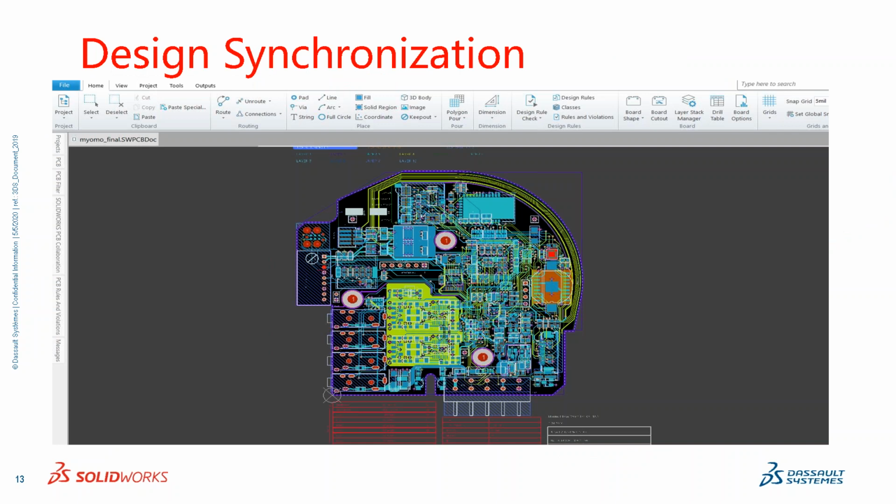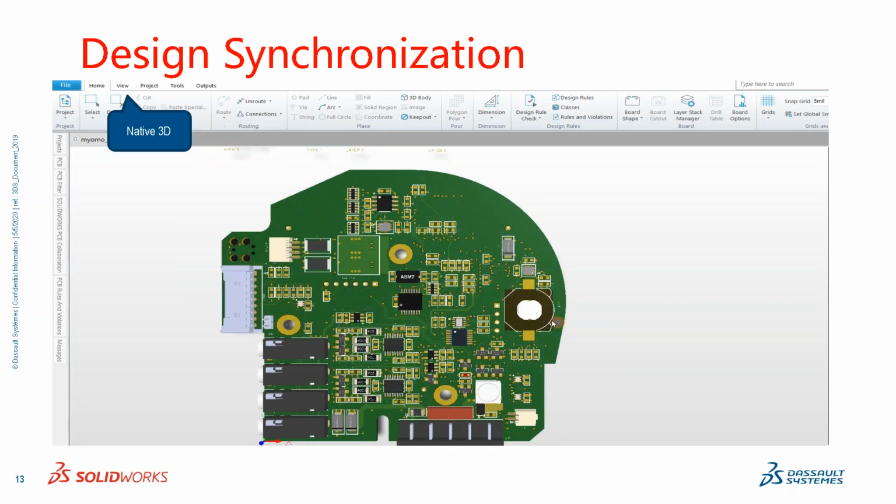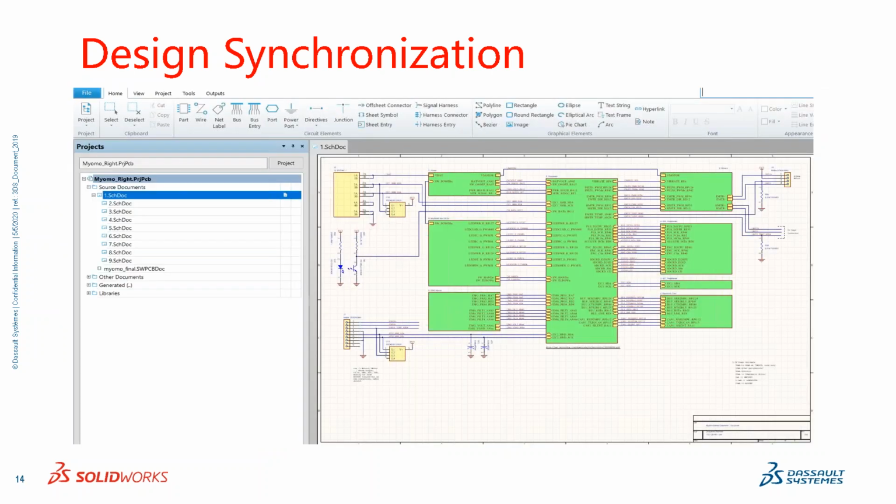And let's take a little deeper dive into some of this PCB aspect. So, inside of here, as I mentioned, we have all types of tools that you're used to working with. Your design rules, your planes, and interactive differential multi-track. You have native 3D built directly into the application so that you can realize your designs in 3D, as well as all of the schematic capture tools that you need to create detailed and accurate schematics paired and linked back to your board layout.